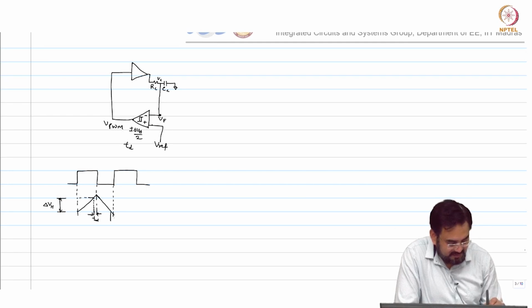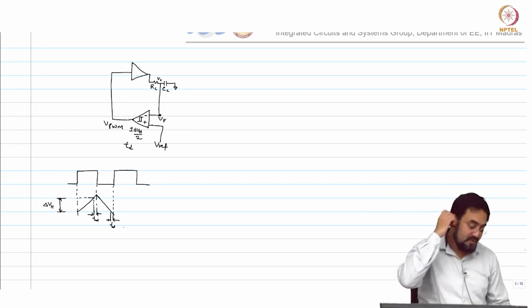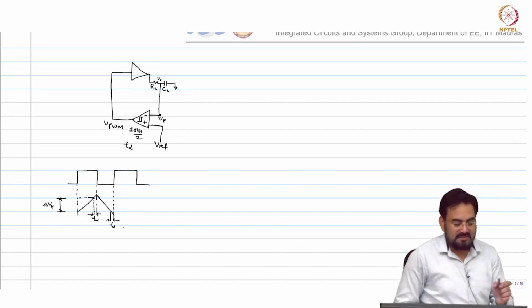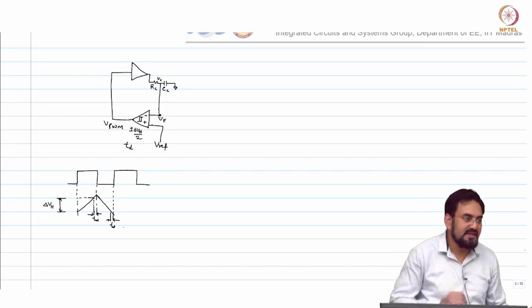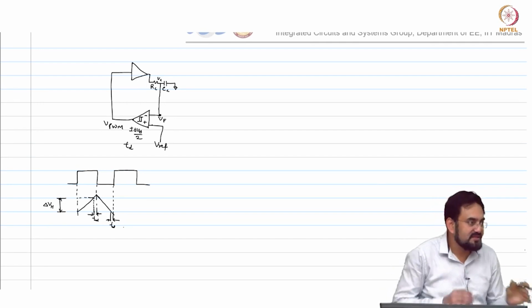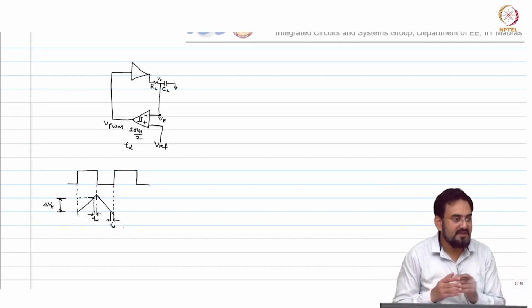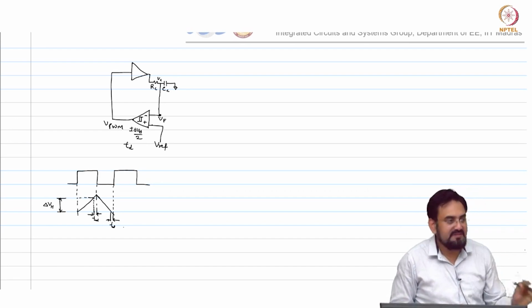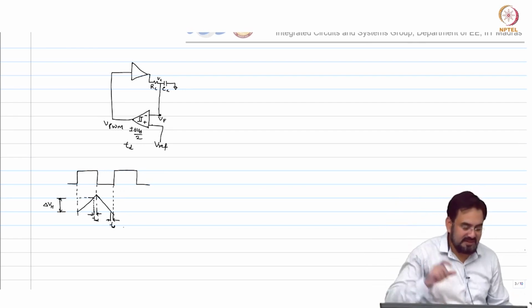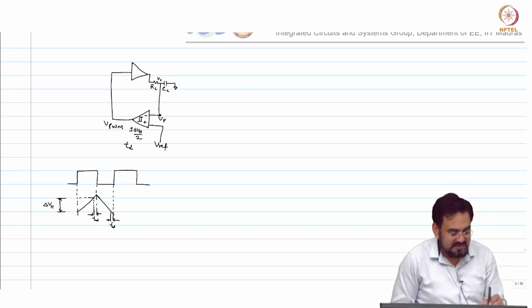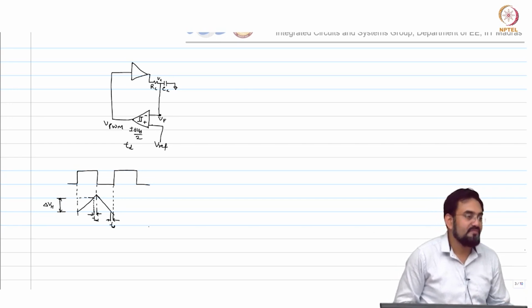This is TD. Here also you have TD. Okay. What does it mean? When your comparator trips, the VPWM will look slightly delayed. So, let us say a comparator goes from high to low. So, the state will not change instantaneously, but after TD delay. Same thing happens when it goes from low to high, which means until that time your VC will keep charging or discharging. So, you will get extra peak and valley, correct, which means, so what if the slopes are same?